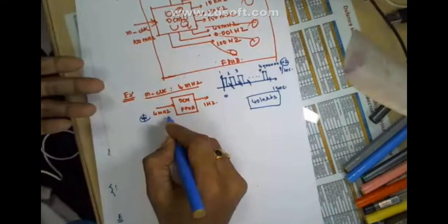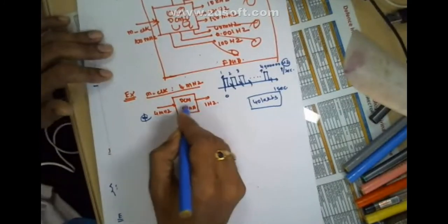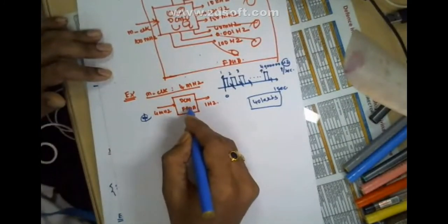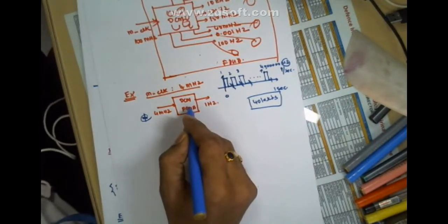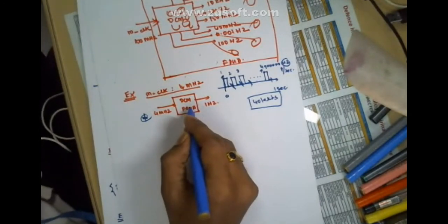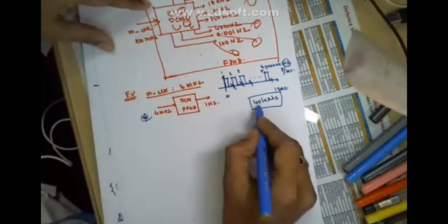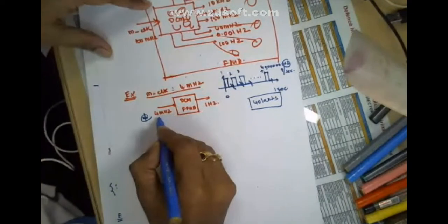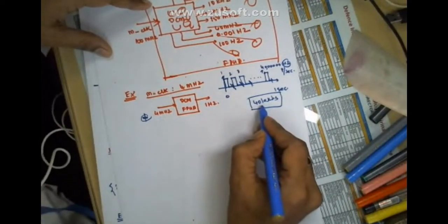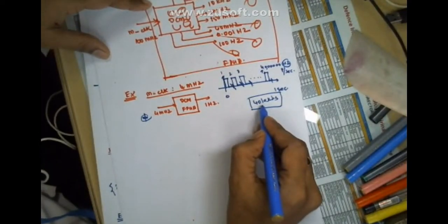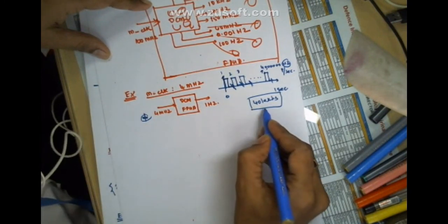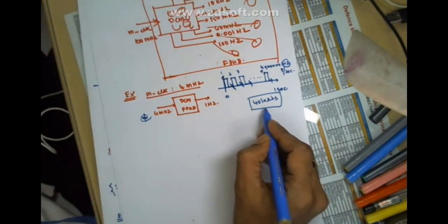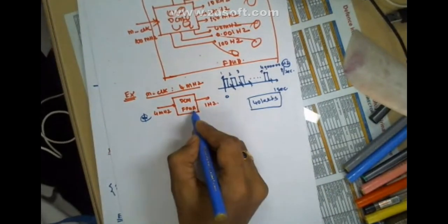Not only 4 megahertz, nowadays this fellow can read 10 gigahertz also, because direct RF digitization is there now. RF SoCs and RF boards are available in ultra large scale integration now. If 4 megahertz is 4 million pulses, then 40 megahertz is 40 million pulses, and 400 megahertz is 400 million pulses going into this FPGA.